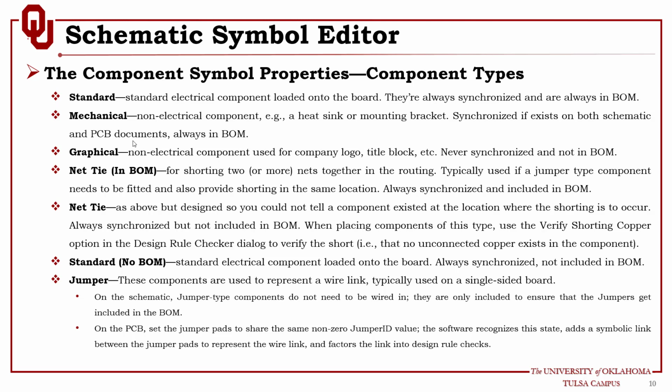Why do you need to do that? Because the ERC, the electrical rule check engine, will not check this component electrically, because this component doesn't have electrical pins. It's just a graphical representation of a mechanical function, and it is defined as a mechanical function as well, and this will be synchronized as well if it exists in both schematic and PCB.